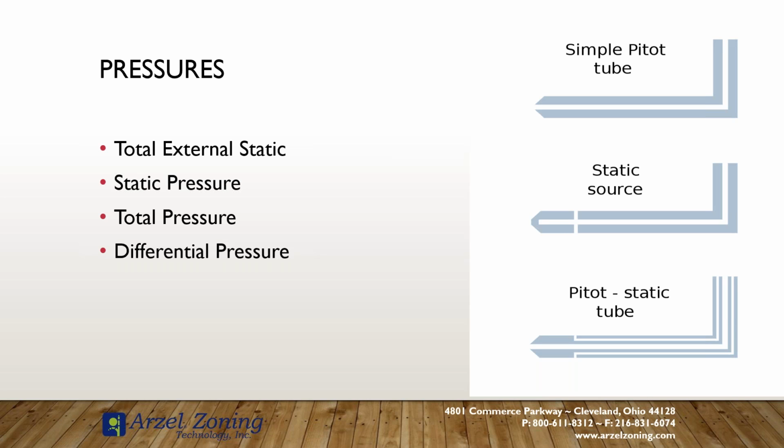But those were means of reading pressures so that we could calculate out our velocity with the manometer or a magnehelic. But being that we have meters, hot wire anemometers, we got the impeller anemometers, like that little Bluetooth dongle that I like. Those give us our feet per minute in real time, so it makes it a lot faster and easier for us, fewer calculations. But our static source tube is going to be our most common tube that we're using for actually measuring to see if our equipment's running outside of its specifications.